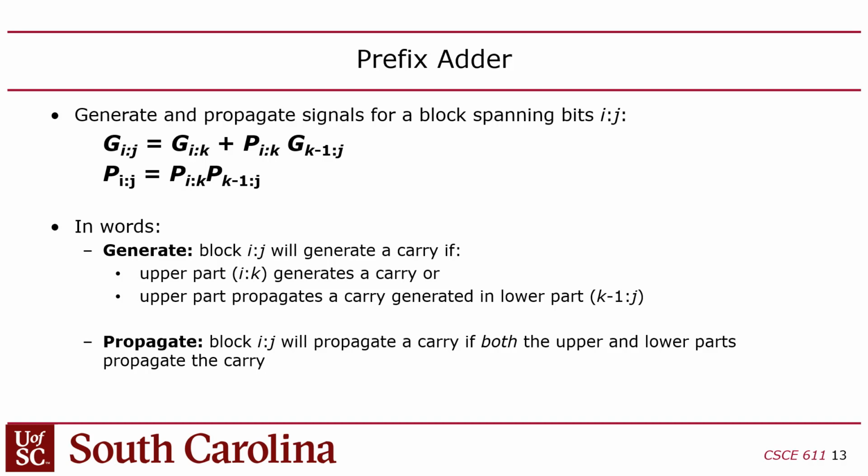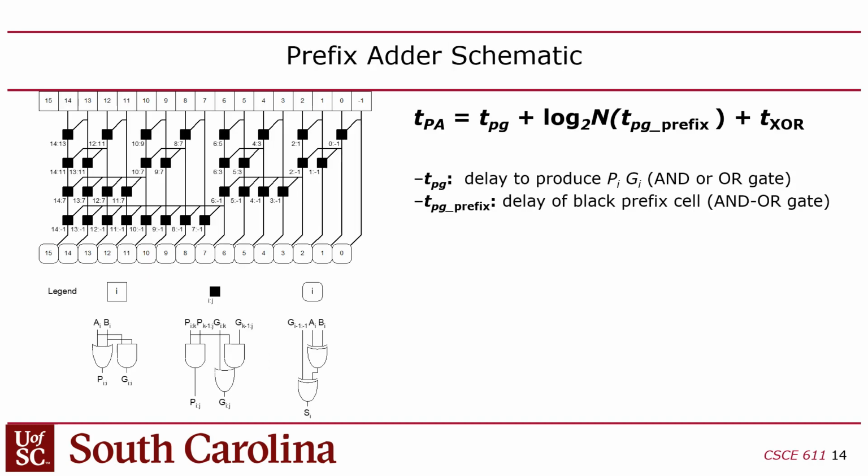So if you have P and G of single bits, you can combine them together to get a 2-bit P and G, but you do it for each pair of inputs. The way you set this up is you start with PG 0 and PG -1, right? And then you have PG 2, PG 1. Now remember, the full adder gives you P and G. It's part of the full adder architecture. Remember we added the single-bit PGs.